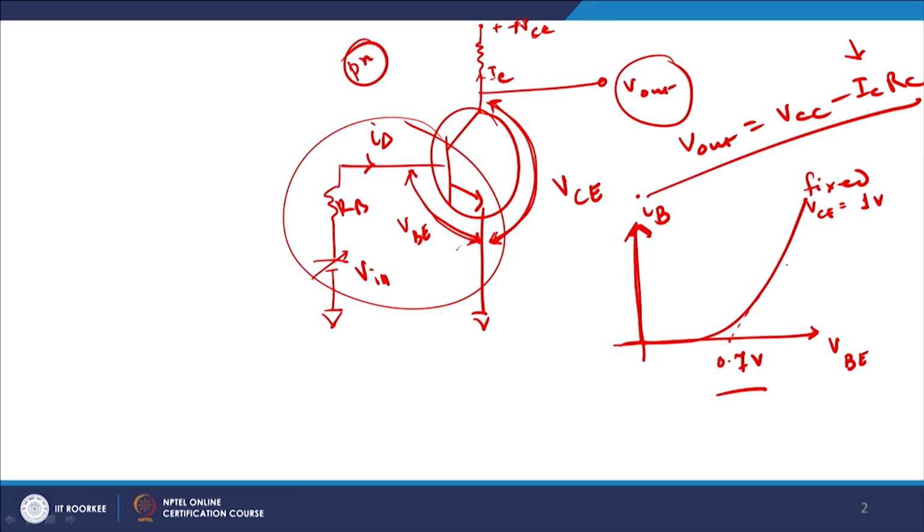If you go on varying the value of VCE, make the VCE larger, I would expect to see a larger current to flow in this case. VCE larger means larger current will start to flow with the same value of VBE, so it will not be like this, it is something like this which you will be seeing, fine. So, this results in an understanding of the input characteristics.